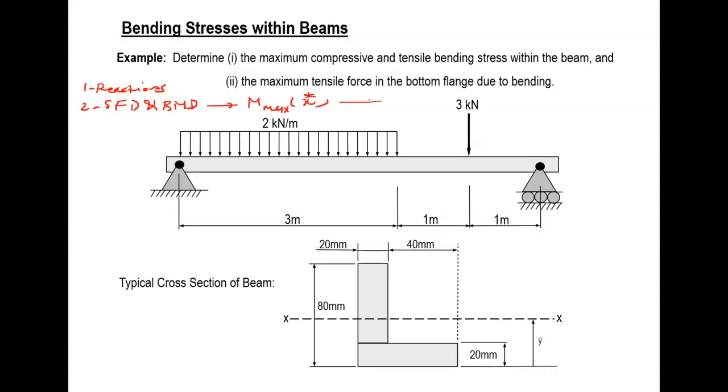From here, I use the flexural formula and find out at what coordinate my internal bending stress is maximum. Okay, so let's get this one started.